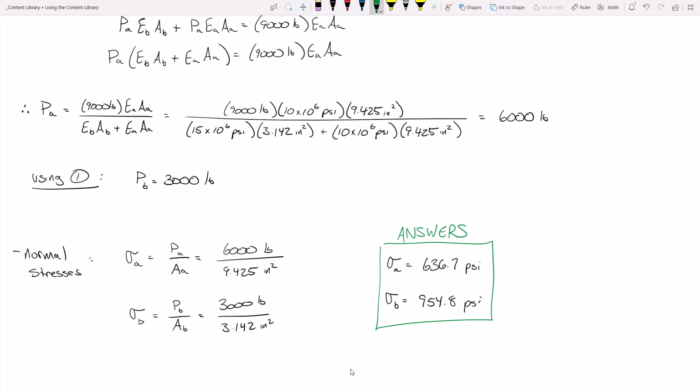So one set of terms I'll start to use in here is the difference between strength and stiffness. Stiffness is the relationship between applied loads and resulting deformations. And so the way that you can characterize stiffness simply is looking at the E value. But strength is the maximum stress it can withstand before failure. So that's like looking at your sigma max or your sigma y and so on. And so I'm not saying that the brass, looking at these data, is stronger than the aluminum. I'm saying it's at least stiffer than the aluminum.